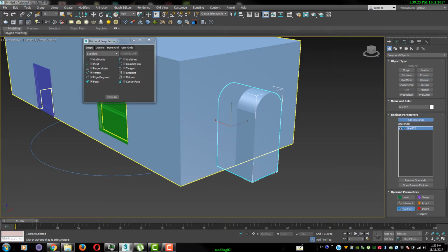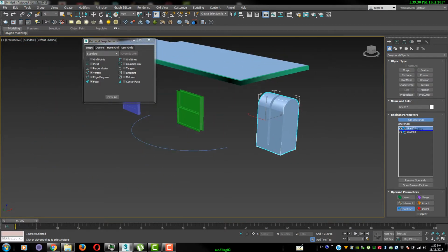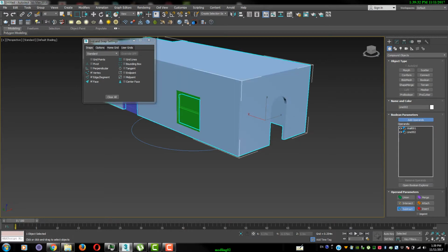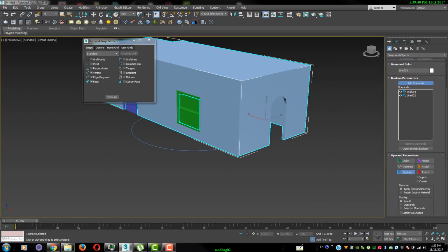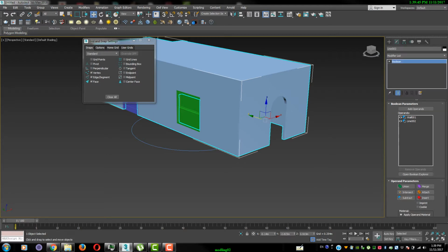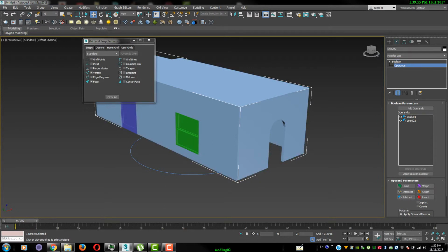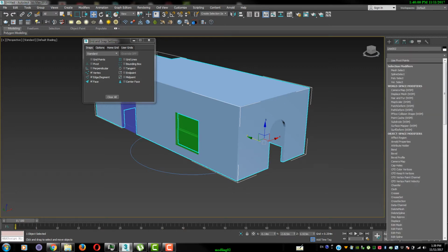And I click. So I select. I want to reverse my selection. Maybe if I, yeah, good. But this option is in 3D Max 2018, but in 2016 and 17 there is the option where you can reverse selection. But now I have a boolean. If I go sub boolean, I have operator. If I double click operator, okay, yeah.